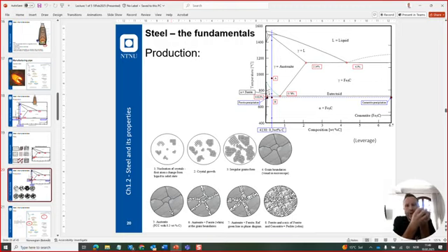It would no longer have the austenitic FCC structure, but on the grain boundaries. Grain boundaries are extremely important for the property of the steel specimen that you're producing. It changes from the FCC austenite to the BCC ferrite, what we just saw a micro picture of on the previous slide.